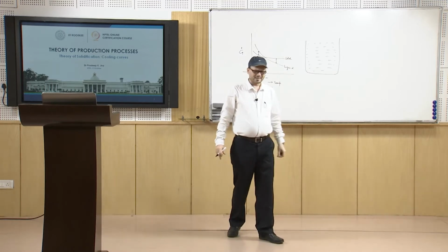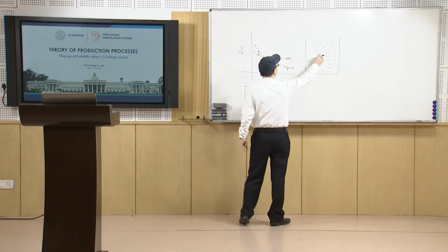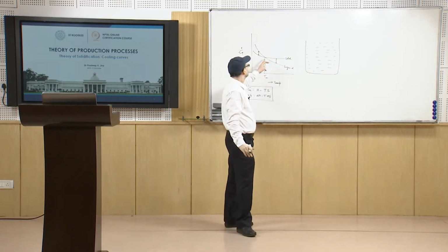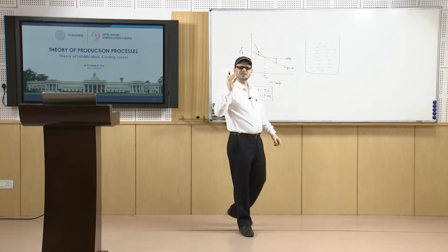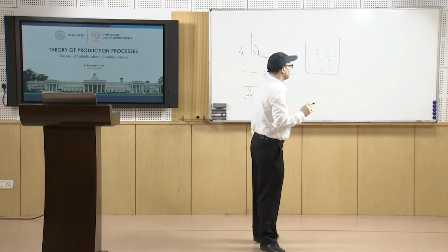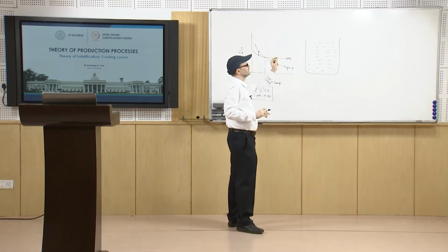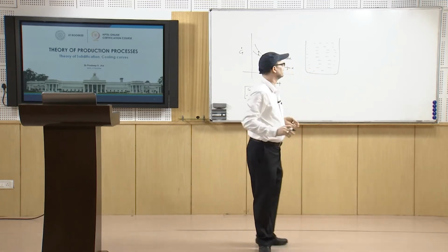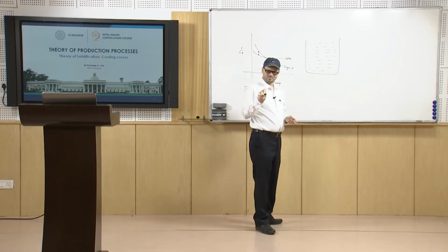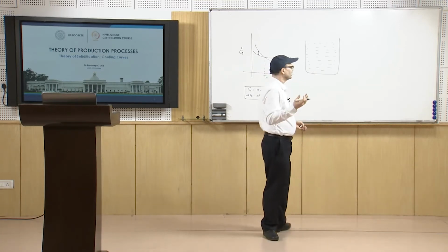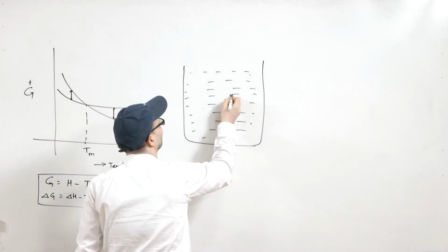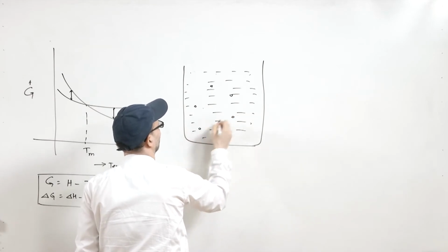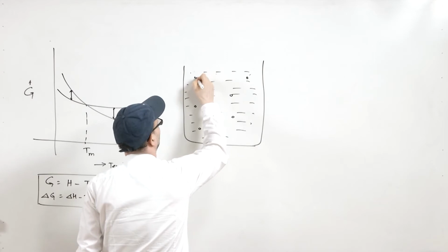Now, as you approach this temperature line and are very close to this temperature, sometimes at some localized place the nucleation starts, or you have the birth of a certain particle. That birth may start somewhere and then go further into the melt. This way, at many places, this birth starts.